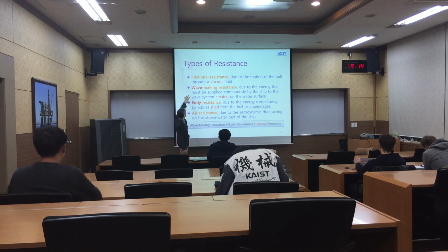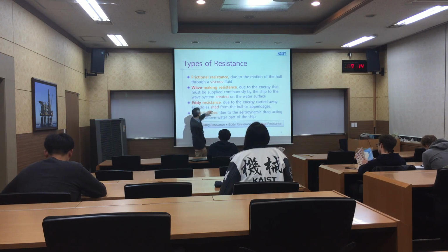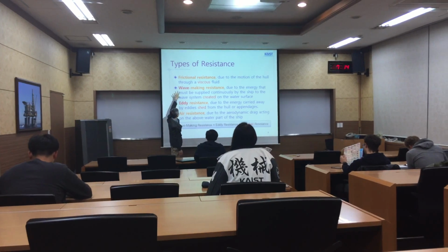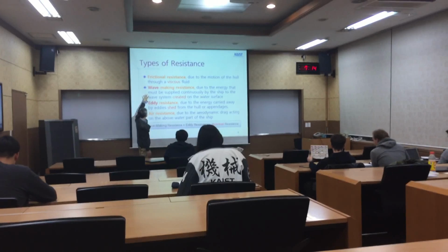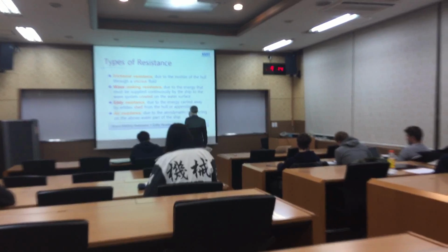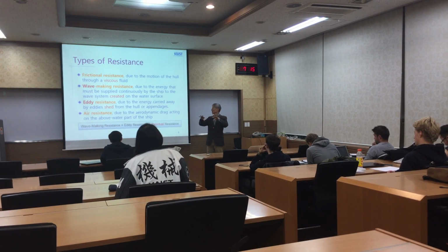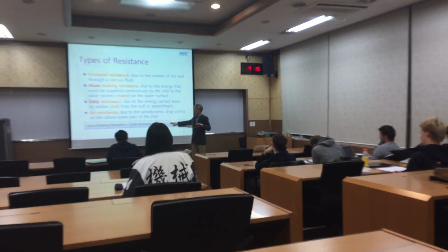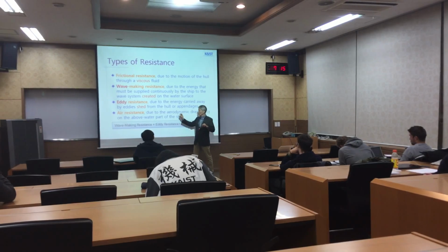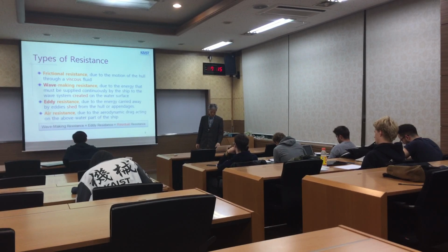And these two can be added to have a name for residual resistance. So by dividing two parts of whole resistance, total resistance is frictional and residual, right? And residual is still further divided into wave making resistance and eddy resistance. Okay.